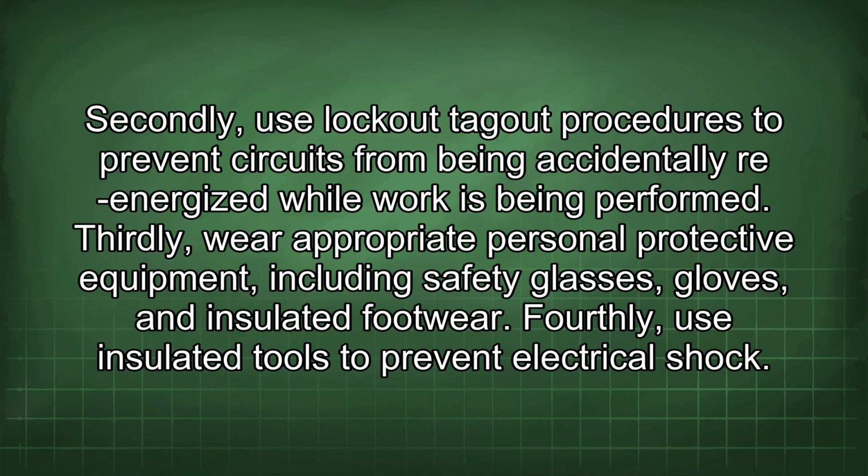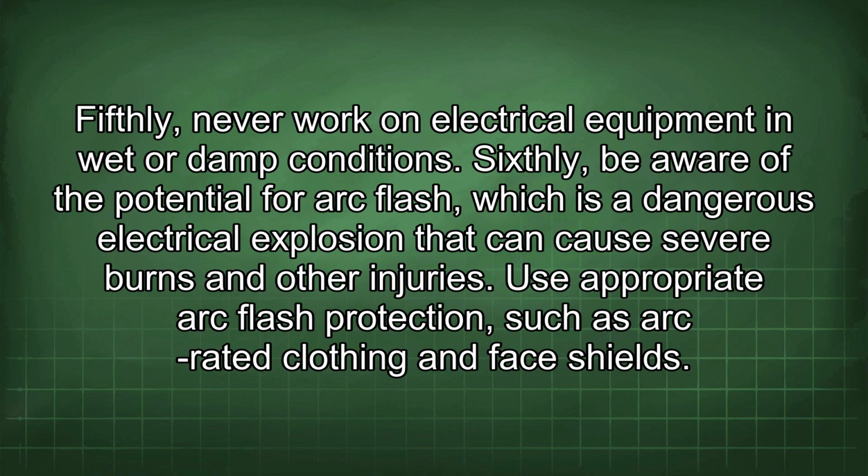Thirdly, wear appropriate personal protective equipment, including safety glasses, gloves, and insulated footwear. Fourthly, use insulated tools to prevent electrical shock. Fifthly, never work on electrical equipment in wet or damp conditions. Sixthly, be aware of the potential for arc flash, which is a dangerous electrical explosion that can cause severe burns and other injuries. Use appropriate arc flash protection, such as arc-rated clothing and face shields.